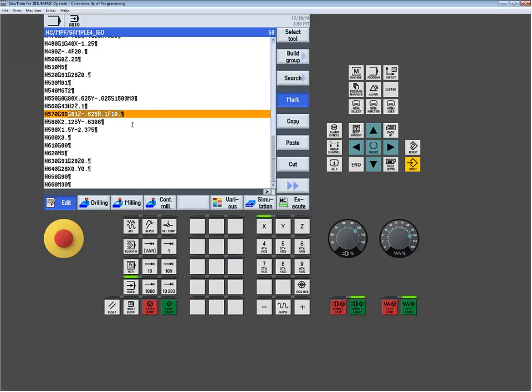We have entire manuals written just for ISO mode that will give you all of the real detailed description of each and every cycle, how they have to be protocoled. From a lathe side, we do support the 3 different protocols in FANUC, A, B, and C. But you do have to set up a parameter in the control to comply with either one of those protocols. I think our default is usually B, if memory serves me. But you can even support those 3 protocols.